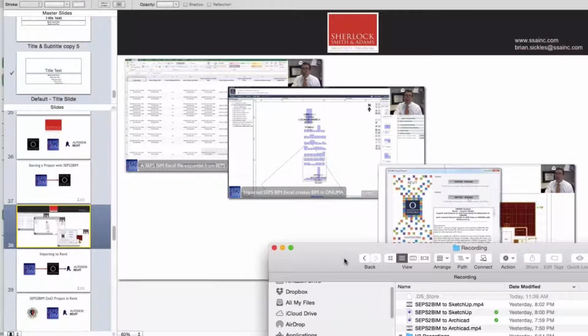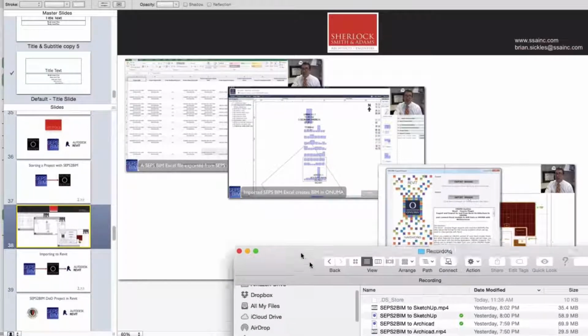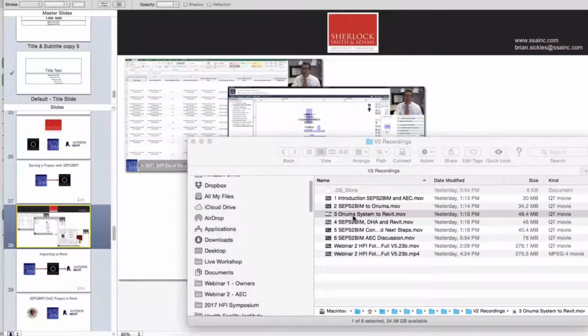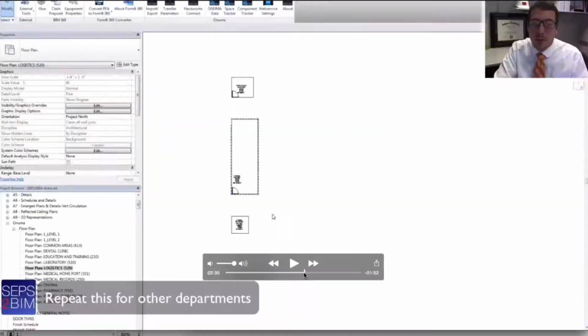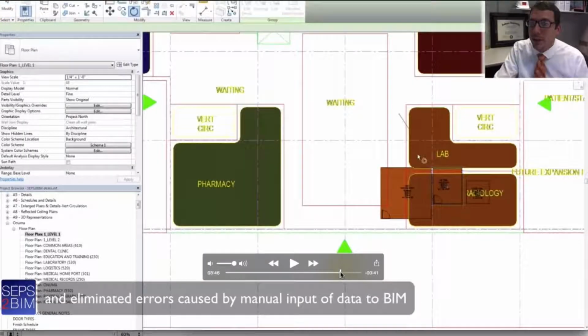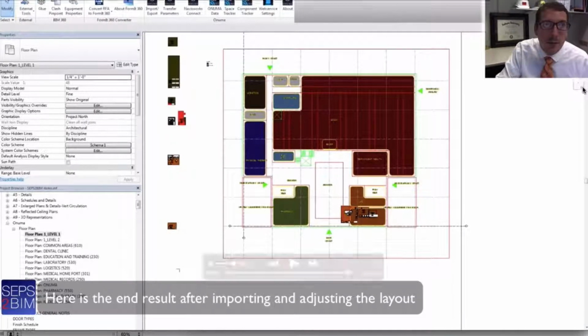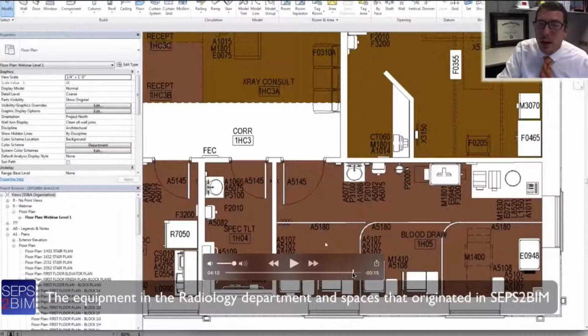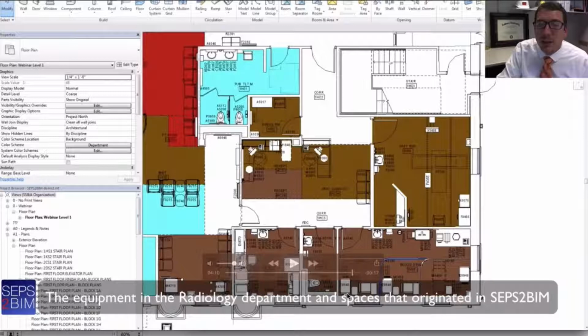They have their square footage requirement. They have their guide plate for how the room should be laid out. If it just works out better that we can make the room 6 inches more narrow and stretch it a little bit here and there to make it work, they typically have the 10% rule, where if you're going to make the room larger or smaller than the program for design, if it's greater than 10%, that's a no-no. And some rooms you have to be right on, and don't have any room for deviation. You have to give them exactly what they show you in the guide plate.